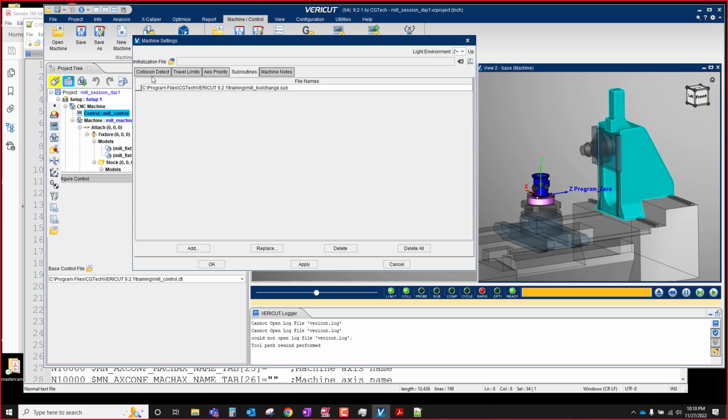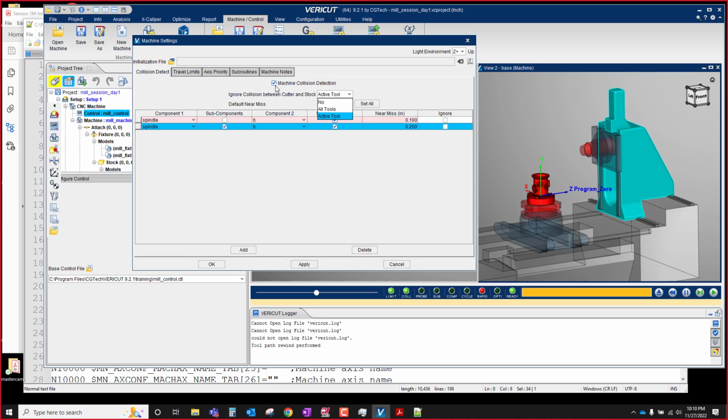It's especially useful on something like a Haas mill with an umbrella tool changer, because you can say, hey, I want to do collision detection between all my tools, because I want to know if anything in my carousel is hitting my part as my table's moving underneath it. Maybe I got a long reamer or something stupid like that. It's just hanging out there. Right. So it's not my spindle, but it's in the work envelope.